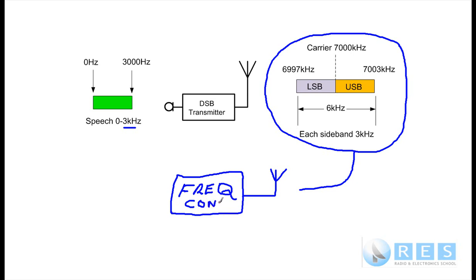If we had a frequency converter, we could simply put this signal into the frequency converter, and we could convert back to audio frequencies, back to audio. Now remember, in the transmitter we did the mixing by using a nonlinear device. So if we're going to do another frequency conversion from these radio frequencies to audio, and that's what radio reception is all about, we're going to need a nonlinear device as well.